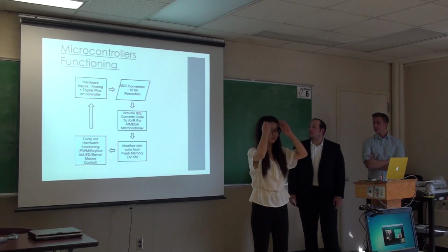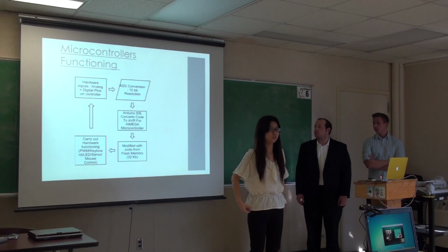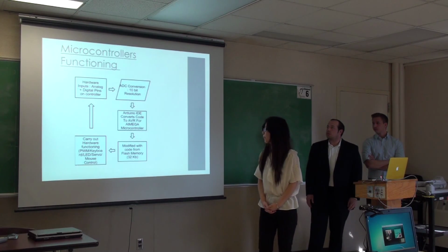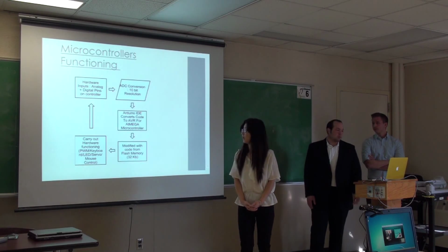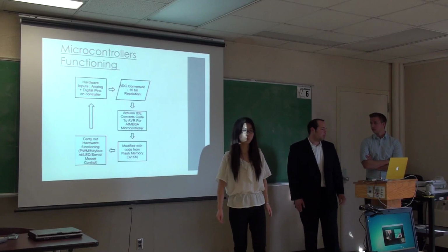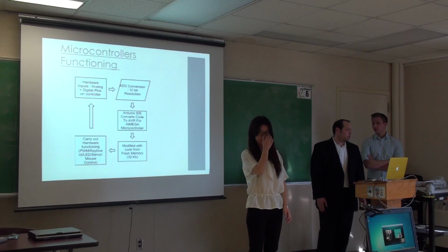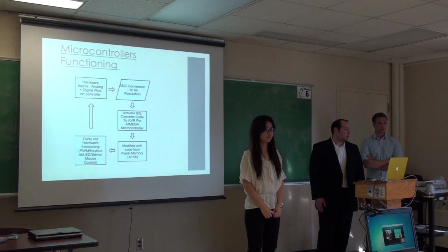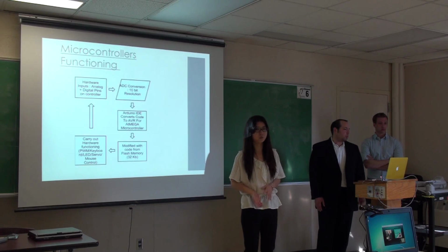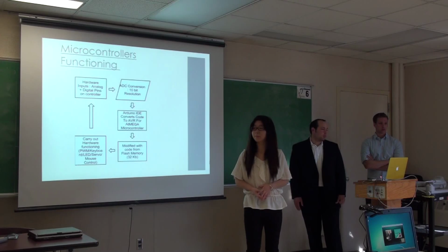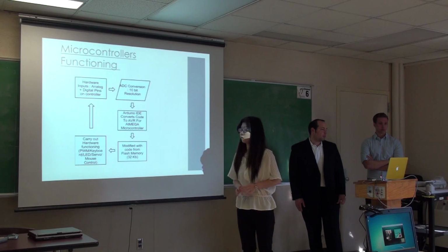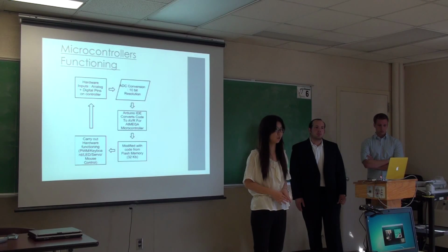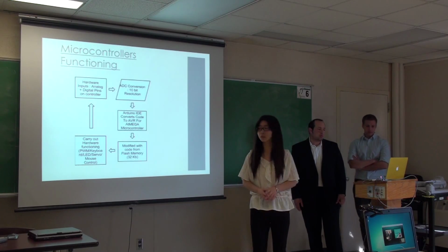Next, I will talk about how the microcontrollers function in the Arduino board. First, any analog input signals, like voltage signals, will be converted to a digital number the Arduino board can understand. With a 10-bit resolution, that means any number between 0 and 1024 will be the result.